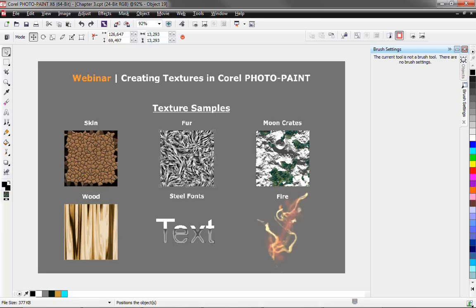I have a larger folder of photos that are textures, all sort of things. What do I do with them in CorelDRAW Graphics Suite? Well, there are several ways to use these textures. You can drag and drop them into your application to use them right away, to paint on them, and if you want to use them as textures, it's probably better to apply them as a pattern fill, I think, bitmap fill.